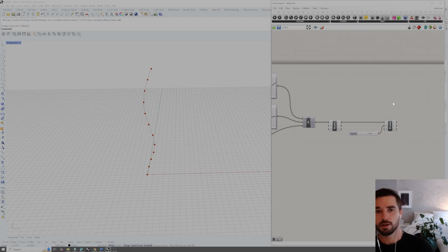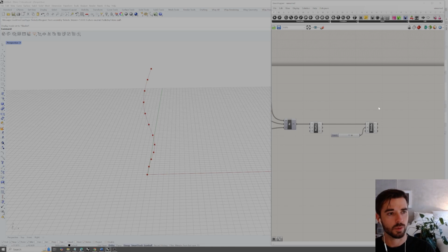Okay. So instead of using this to loft with another curve, what we're going to do is basically construct a parametric sweeping function inside of Grasshopper. So we're not going to use sweep. We could very well use sweep, but to get this kind of parametric control or finer grain control, what I tend to do is build up these curve divisions and manually place the sections along this curve so that we can rotate each individual section, getting twisting or scaling actions happening throughout the section. So that means we could taper at any moment, or we could expand at any moment, and it makes these sweep actions incredibly dynamic.